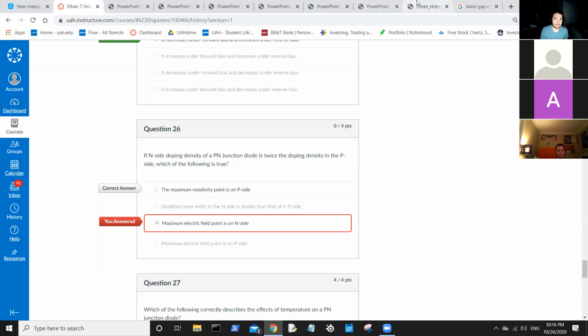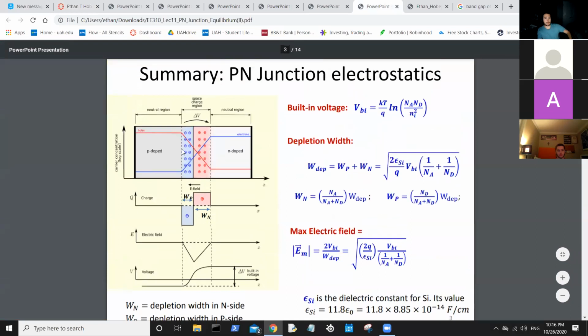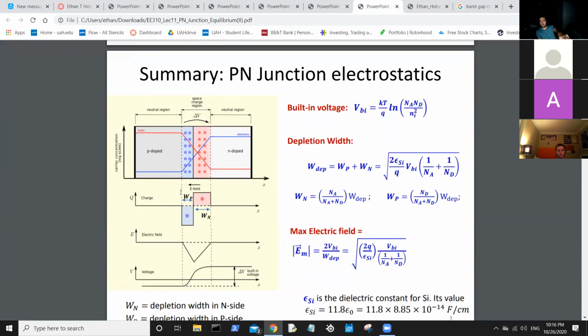So let's look at this. In this one, this is actually the direct inverse of that question. Obviously here, the P has the higher doping density, but either way, we can use this as an example. Look, you see where those carriers are equal, where they cross each other, and it's not at the junction point? That, where those carriers are equal to each other, is the highest resistivity.